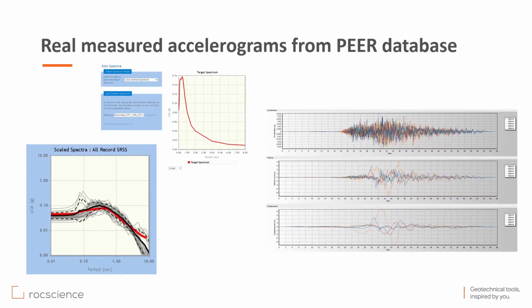And as a next step, we also used the calculated response spectra as target spectra for the next steps. In the next step, we downloaded some real measured time series from the online database of the Pacific Earthquake Engineering Research Center, the NGA West 2 database.